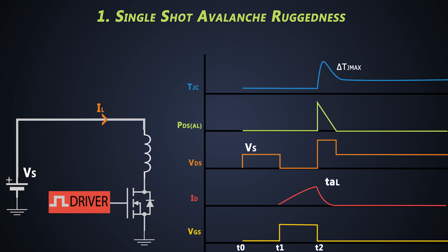As we can see, the drain to source voltage on the MOSFET increases at a remarkable rate, and our MOSFET should handle this drain to source voltage. It should not go into breakdown. So generally, the breakdown voltage of any MOSFET is 1.3 times its actual VDS rating. For example, if there is a 60 volt MOSFET, then its breakdown voltage will be around 78 volts.